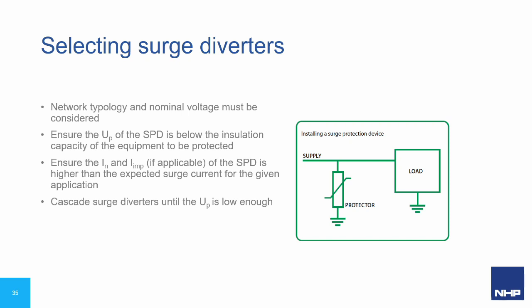So to help us understand the correct application of surge protection, it is useful to remind ourselves of the fundamental purpose of surge protection, and that is the prevention of hazardous potential differences. Many people get caught up with industry buzz terms or simply believe that the most important feature of a surge diverter is its ability to conduct current. However, what use is this feature if the surge diverter doesn't limit the voltage to a suitable level, a level which the installed equipment can sustain?